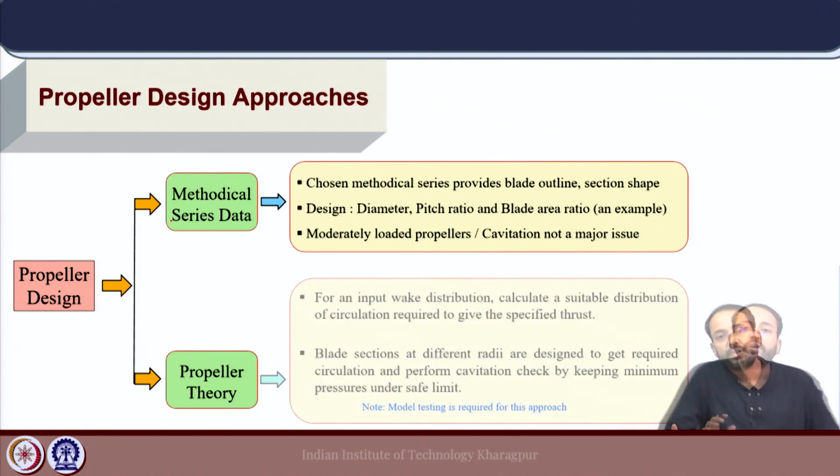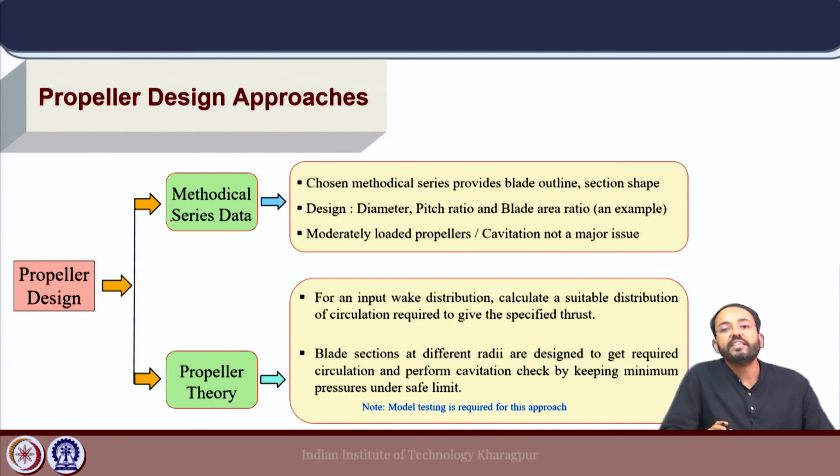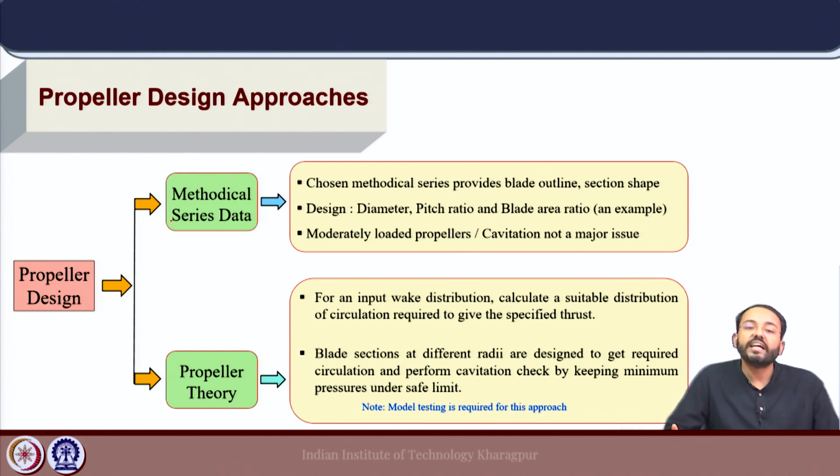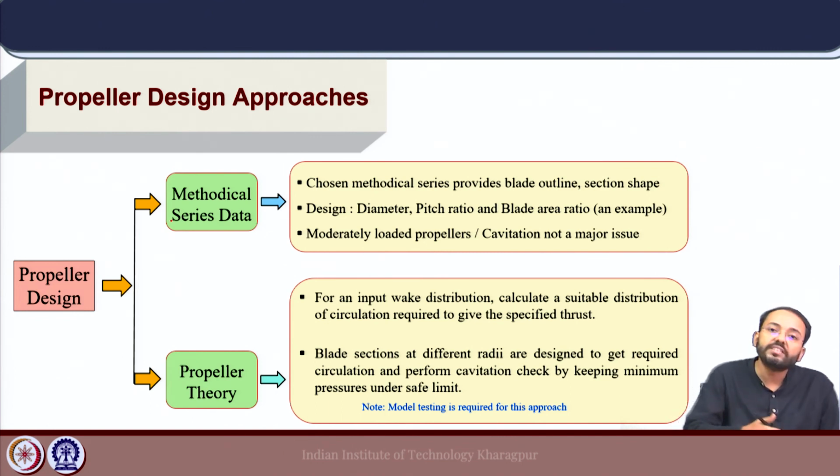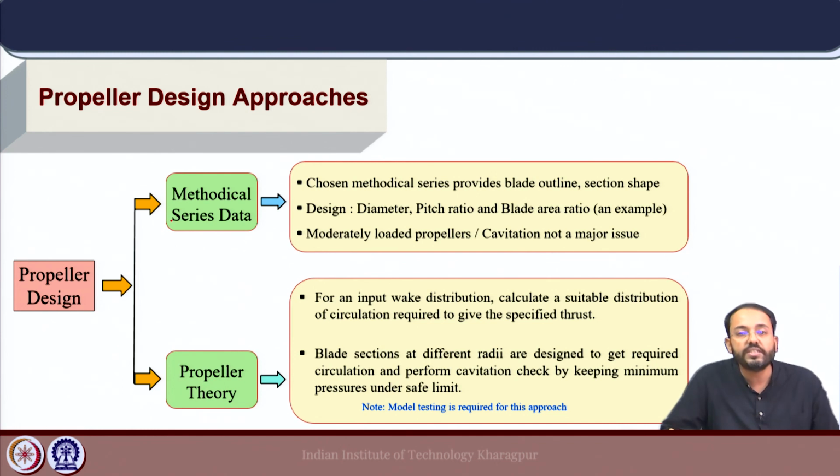On the other hand, we have the circulation theory based design for propellers, where based on an input wake distribution, a suitable distribution of circulation can be assumed to obtain the specified thrust. And here model testing is required because the designs that are the output of this approach are new, because there is no methodical series which is used here, and the designer can choose different types of blade sections to develop the design, and one can do model testing to validate the outcome of that design with respect to the propeller performance.